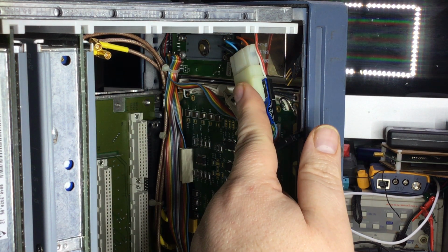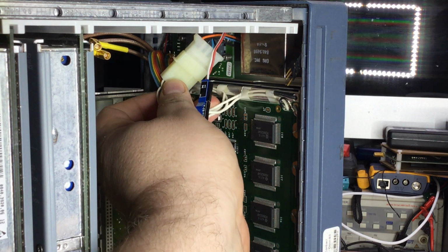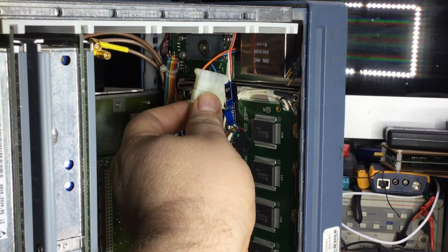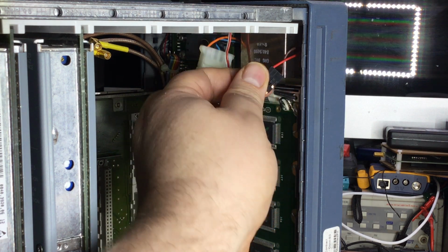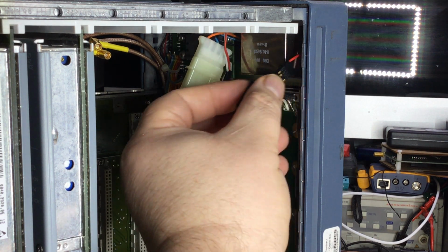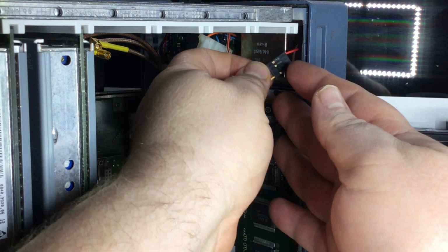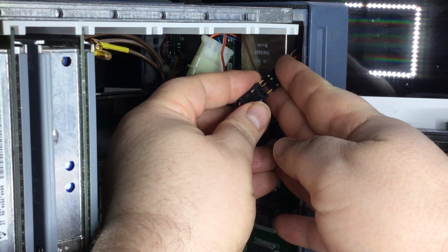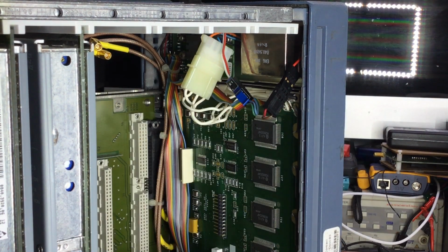But that particular backlight is powered, this module, by this connector here. And this connector just literally, as I was taking the module out, just fell apart. Now, what's strange about it is that when you connect the connector back together, and this connector provides power to the inverter module.